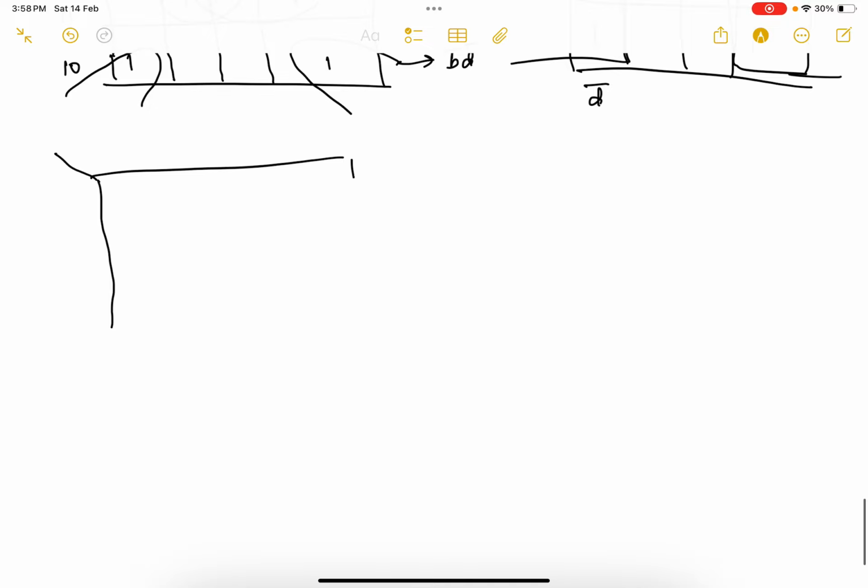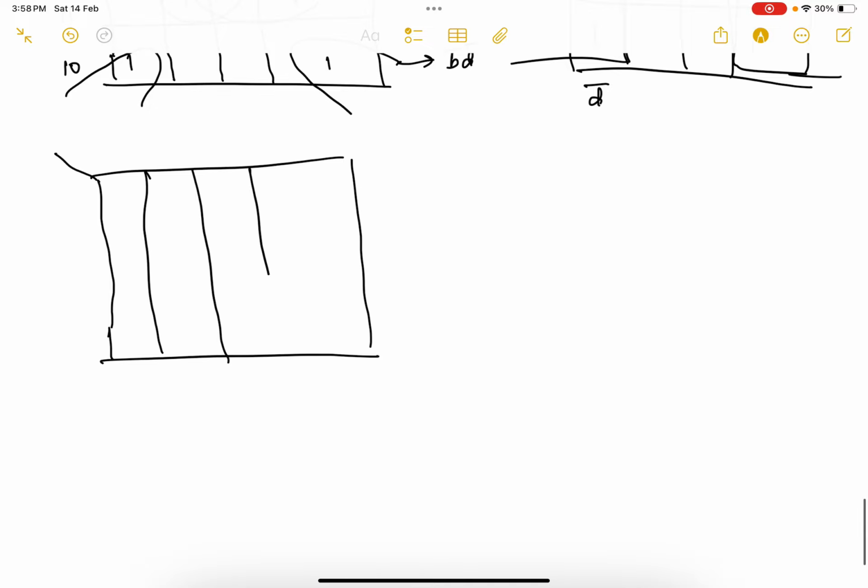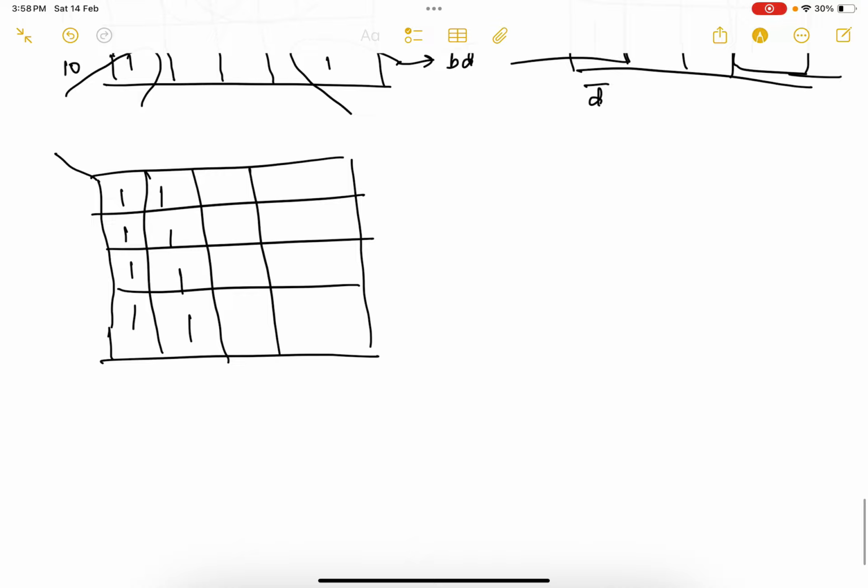Here we will go with some more examples. For example, if we had a structure like this, what is the answer? This is 0 0, 0 1, so this will form one more quad. So the answer will be what? This is C bar D bar, this is C bar D. The common term is nothing but C bar. C bar is the answer.